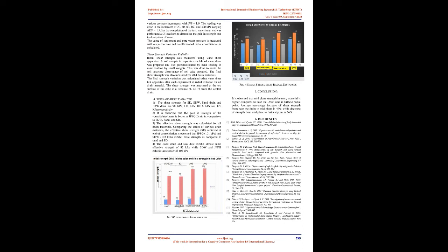The clay was then scribed level, and a filter paper followed by a porous stone was placed at the top. The sample was then pre-consolidated under gradually applied static dead load of 8 kPa, with ΔP/P equals 1, in increments of 1 kPa, 2 kPa, 4 kPa, 8 kPa, so that the consolidation occurring is normal.